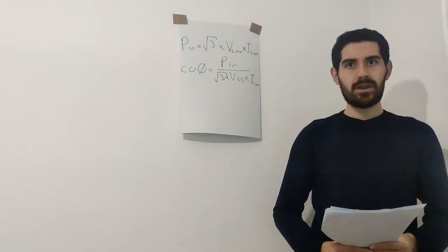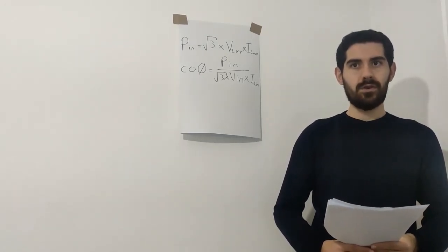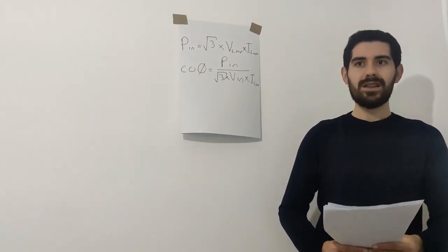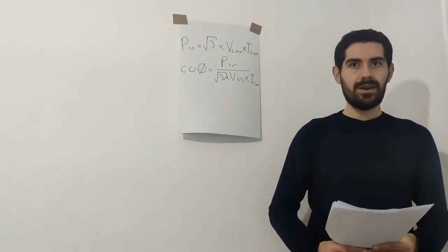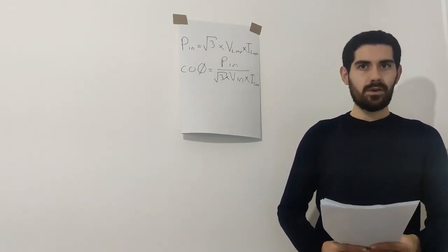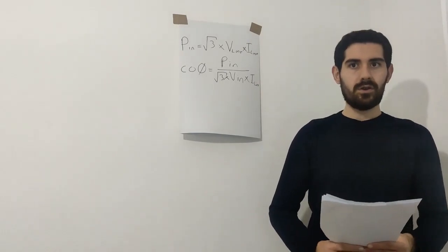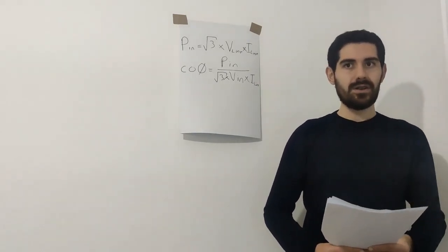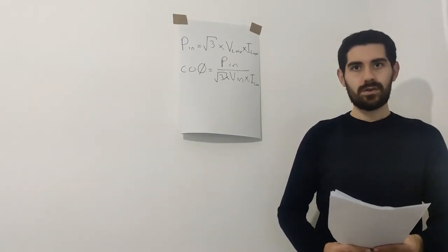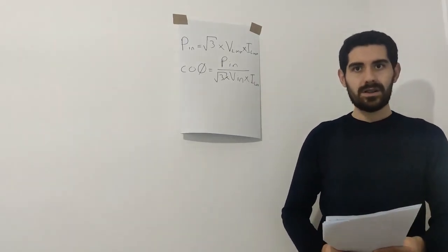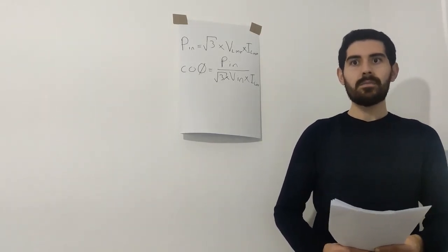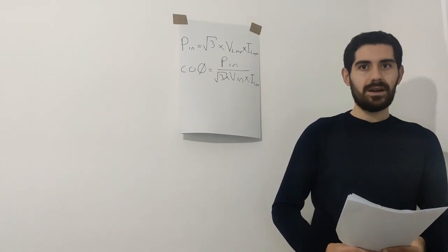The power factor of induction motors with load varies typically from around 0.85 or 0.90 at full load, to as low as about 0.20 at no load. At no load, an induction motor draws a large magnetizing current and a small active component to meet the no load losses. Therefore, the induction motor takes a high no load current lagging the applied voltage by a large angle.